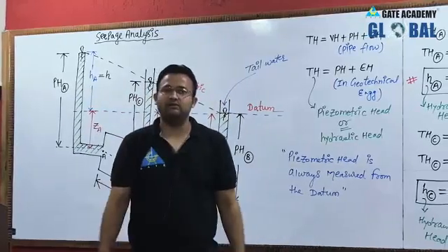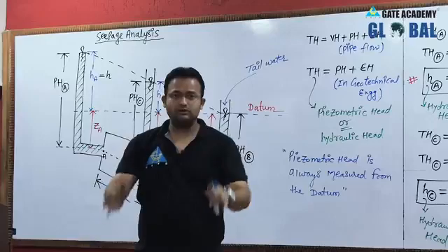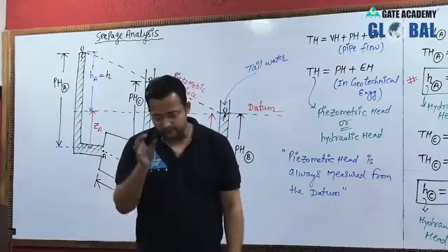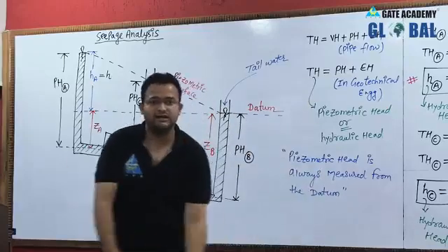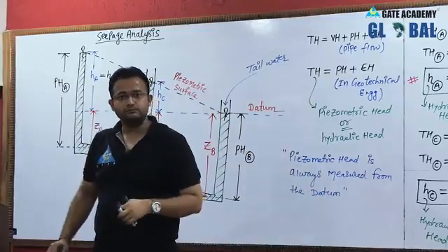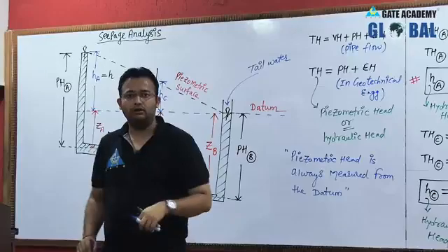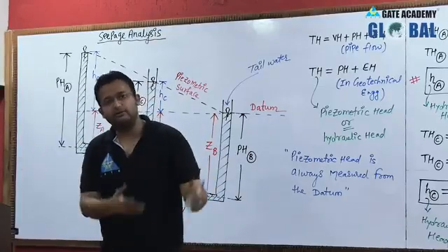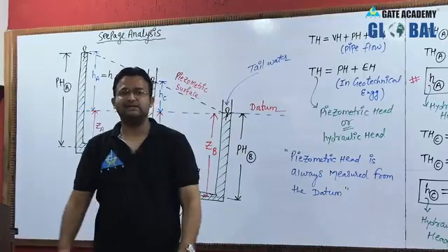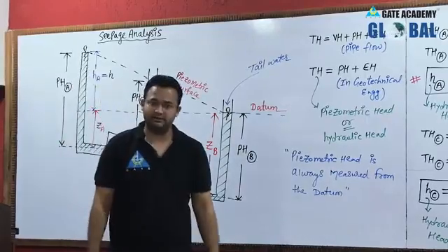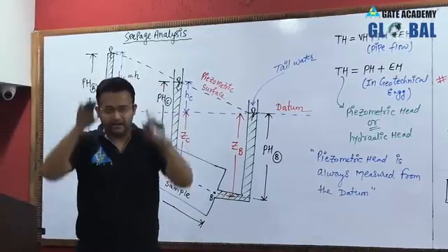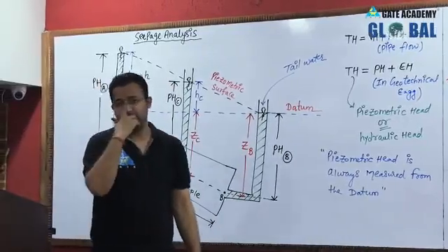Your structure may fail. Your structure is resting on the ground and below the ground soil is present. If the soil is flowing with the underground water, then after some time there will be no soil below the ground, and your structure will settle down. Who will take the load of the structure? Because soil is not there, it has already flowed, so the entire structure will get settled, your structure may collapse.